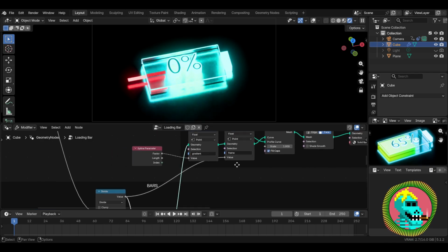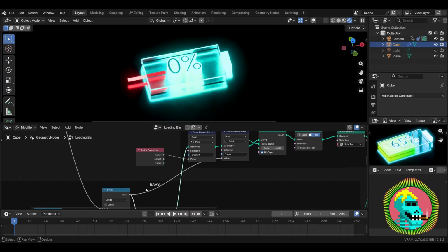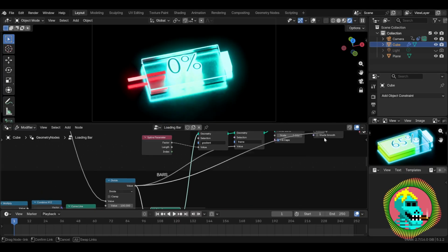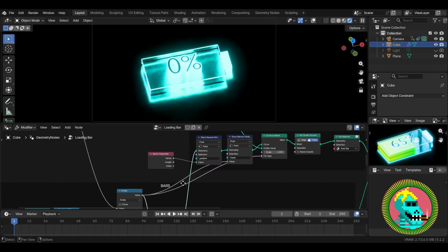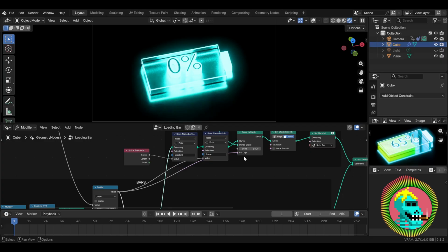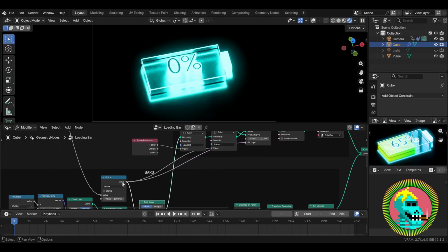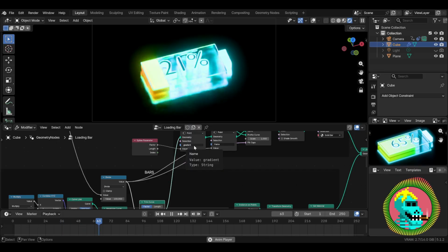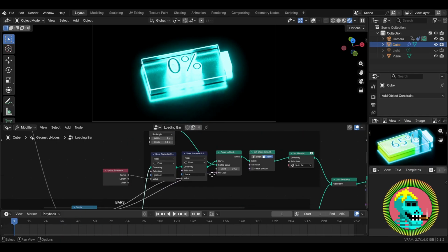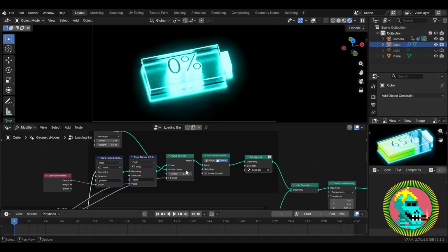To ensure that the filling of the side faces is used only at the right moments, we'll use the value that the divide node gives us. At the very beginning the value is 0, which means no. And as soon as the value becomes slightly greater than 0, it means yes. Accordingly, on the initial first frame there is no filling of the caps, but in the next frame this filling already occurs. And now it works as we need.